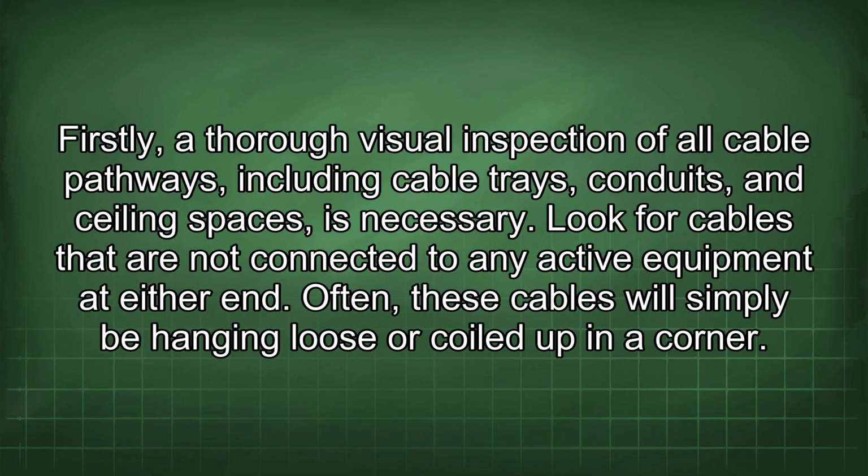Firstly, a thorough visual inspection of all cable pathways, including cable trays, conduits, and ceiling spaces, is necessary. Look for cables that are not connected to any active equipment at either end. Often, these cables will simply be hanging loose or coiled up in a corner.